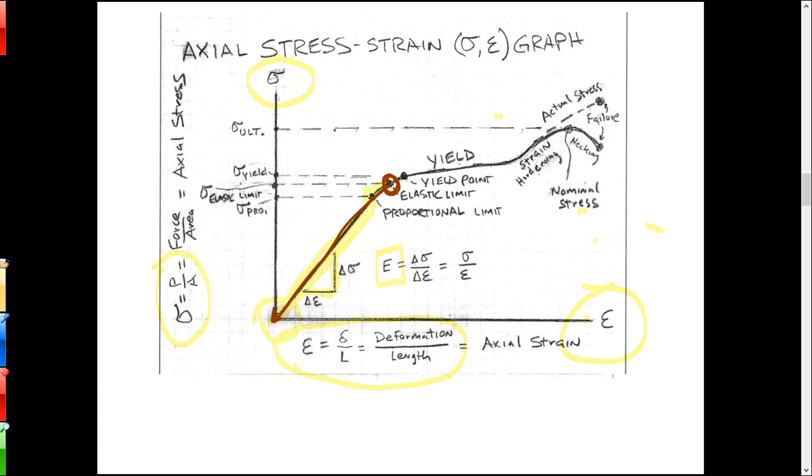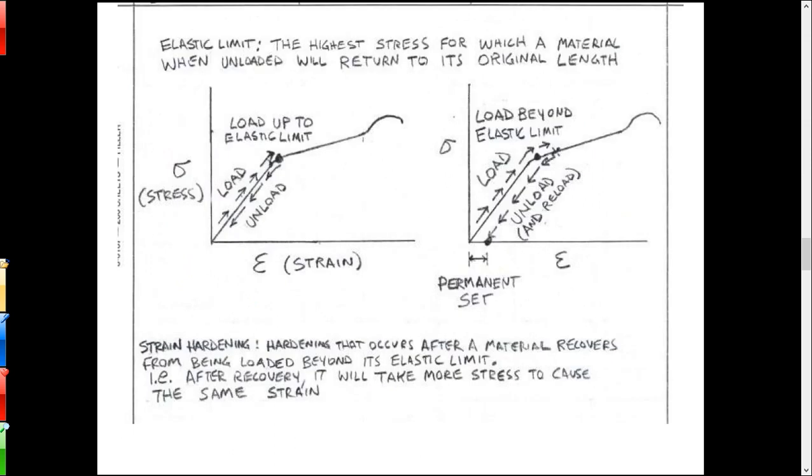If you go beyond the elastic limit, it won't. If you go beyond the elastic limit, the material will unload and have a permanent set in it. You'll stretch it a little bit. You'll deform those atomic bonds, and they won't be able to get back to where they were. That's on the next page there.